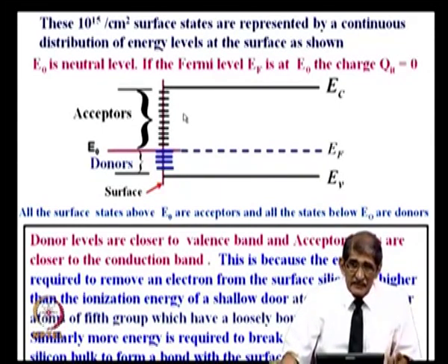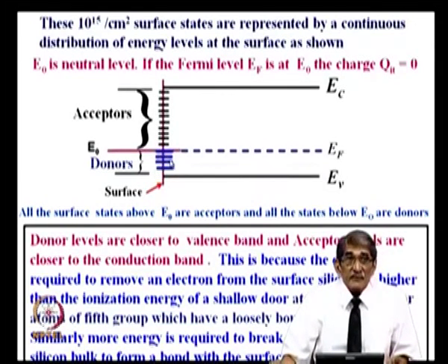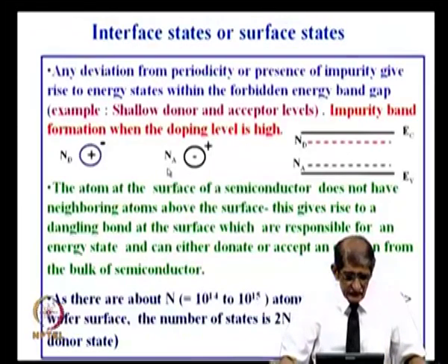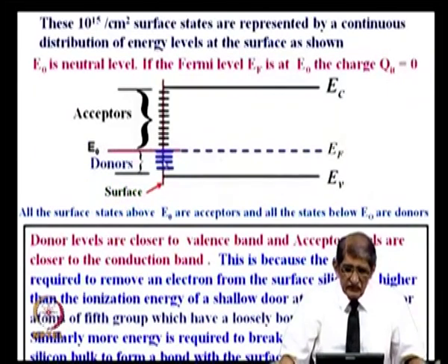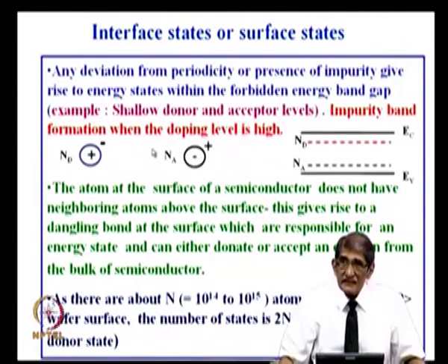Now, go back to what I mentioned. All the donor levels are occupied because they are below the Fermi level. So, what is the charge state of that? Just go to this and see, they are occupied, which means it is neutral. So, these levels are neutral because they are all occupied, and the acceptor levels are not occupied by electrons, which means that is neutral. If it is occupied, it is negatively charged.